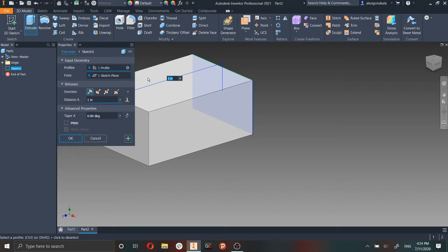So you don't want to get into that bad habit. You want to know what is actually happening, and then you can take a shortcut later on if you want. But I suggest, starting out, to do the start sketch, then finish sketch, and then extrude, and whatever other things you're doing in between those. And yeah, it's going to be the same thing.